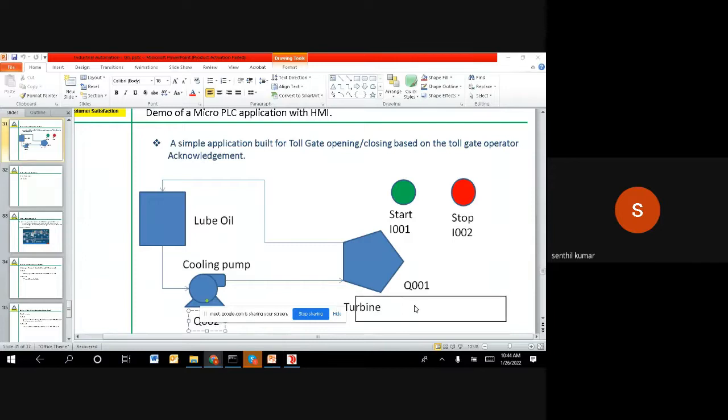Right. So far what we have seen are the logic gates AND, OR, NOT, NAND and the set-reset flip flop. Then we have seen the timers. In the timers, the important things are the on delay timer and the off delay timer. There are other timers also, like the on-off cycle timer and the weekly timer, and multiple options are there, but those are very rarely used actually.